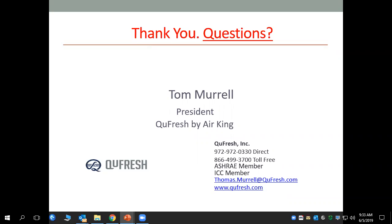So I just want to elaborate a little bit on, in your opinion, where you think those CFM rates are. Are they based on worst case scenario? Even if a house is testing at 3 air changes an hour, if it's a 5,000 square foot house, a 6,000 square foot house, if it's right at 3 air changes an hour, are you getting enough natural infiltration as it is? Just your general thoughts about the new formula on 62.2, the required CFM rates in general.